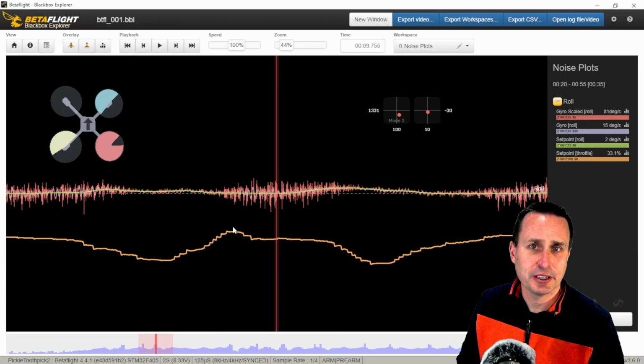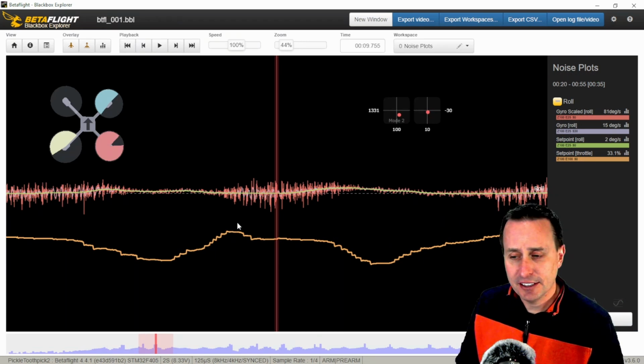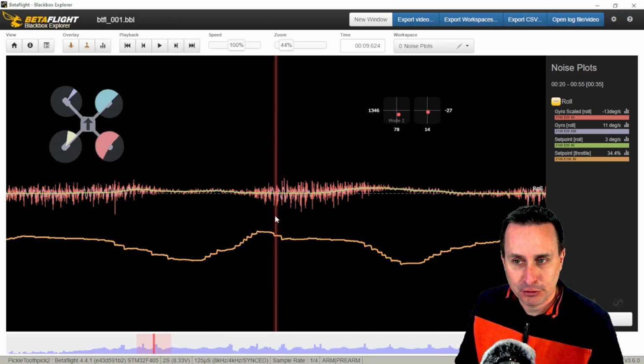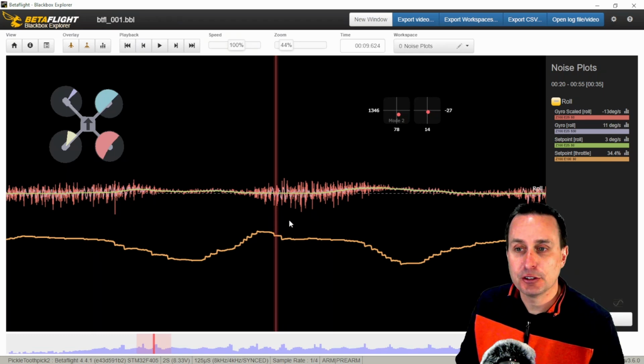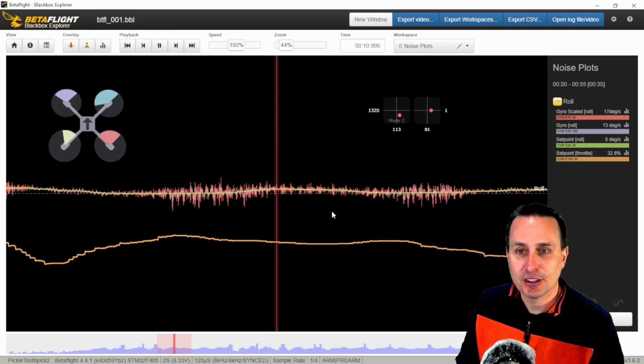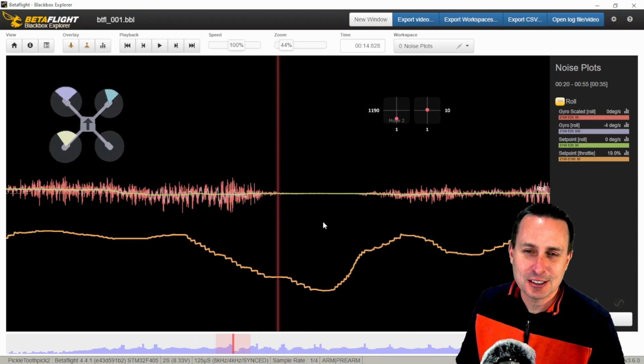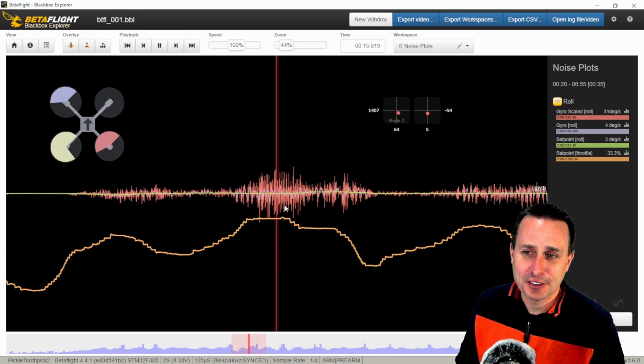Again, check the flight controller, make sure things aren't hitting it, make sure it's nice and tight, that it didn't come loose in the stack. Just give it a good mechanical going through. Then if it still is the issue, I would drop the PID gains down so they're high 40, see if that helps, or if it's almost like covering it up if you still might have this issue.